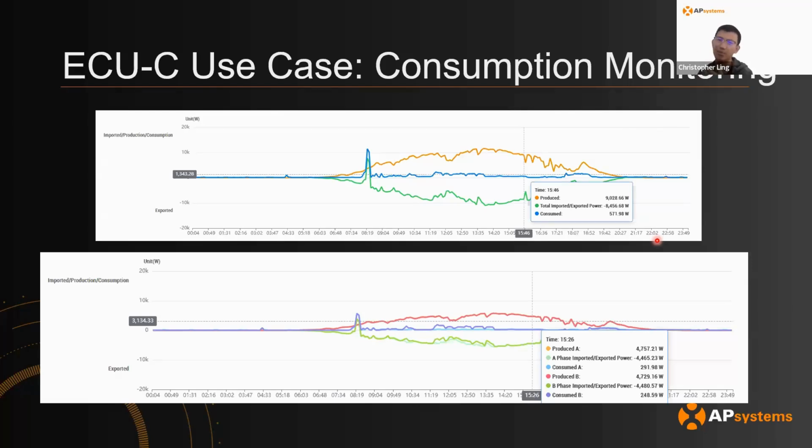The longer answer is it is possible to use higher rated CTs. The main thing is that the CT ratio will be different from what we normally use. I think it's on the data sheet. I want to say we use 3000 to 1 current ratios. But it is possible to use other current ratios.